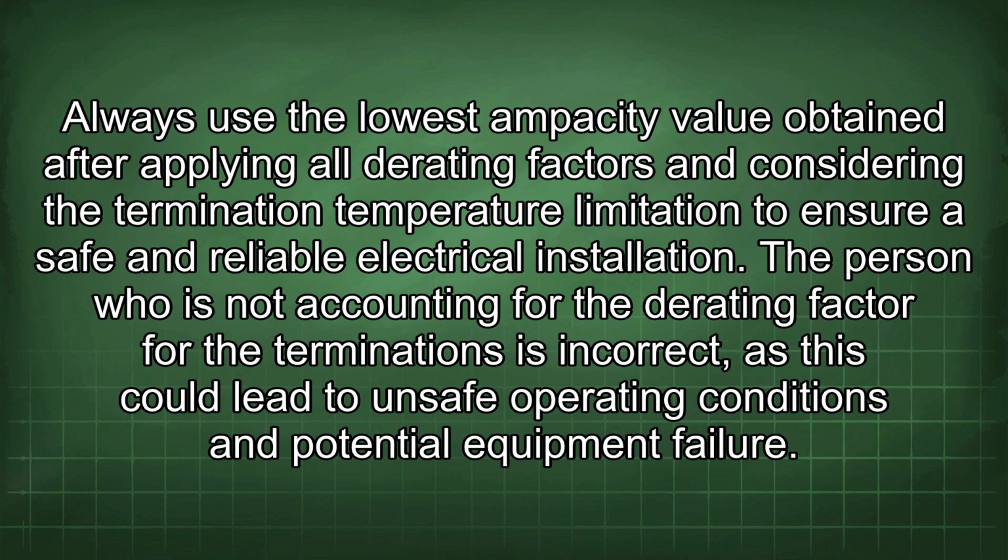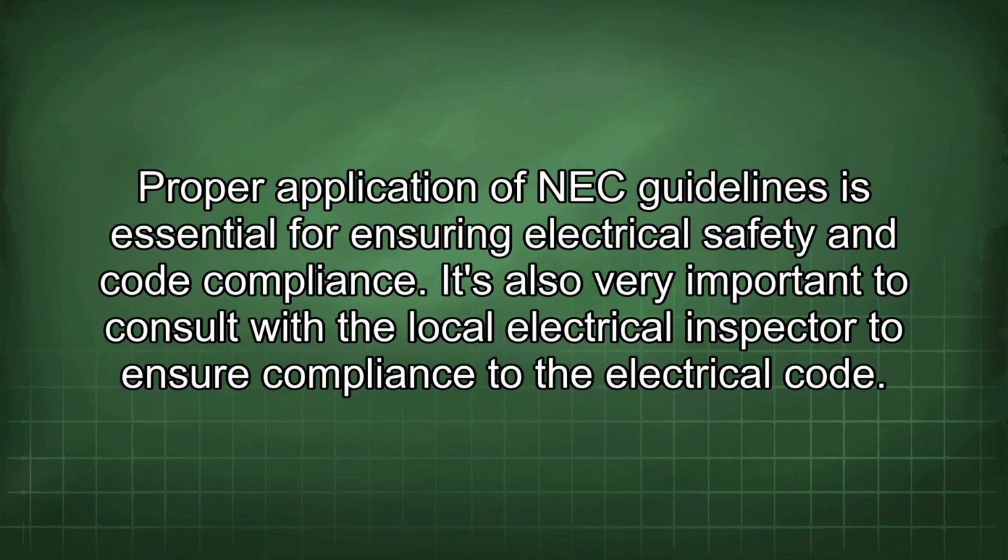The person who is not accounting for the derating factor for the terminations is incorrect, as this could lead to unsafe operating conditions and potential equipment failure. Proper application of NEC guidelines is essential for ensuring electrical safety and code compliance. It's also very important to consult with the local electrical inspector to ensure compliance with the electrical code.